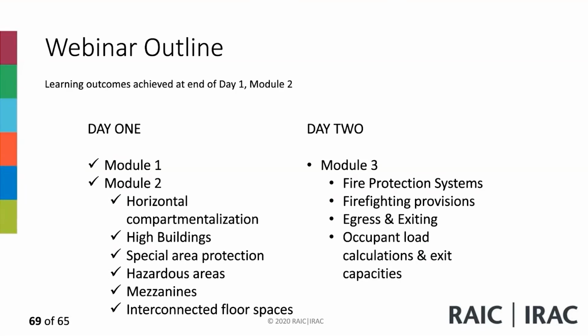So let's go back to 322 to look at an example of a mezzanine specification. Typically mezzanines are required to have a fire resistance rating. For example, 32284 tells me that a mezzanine shall have, if of combustible construction, a fire resistance rating not less than 45 minutes. It's not a fire separation in this case, just a fire resistance. But that's for your mezzanine, which is your first level.